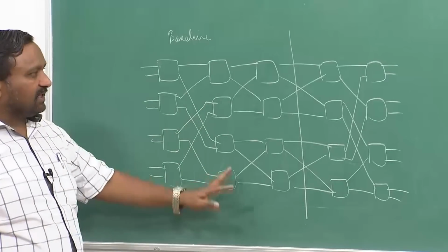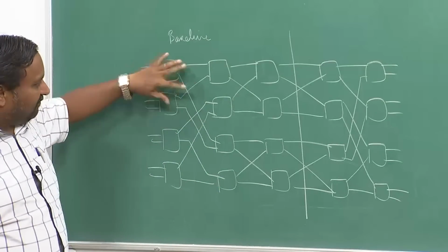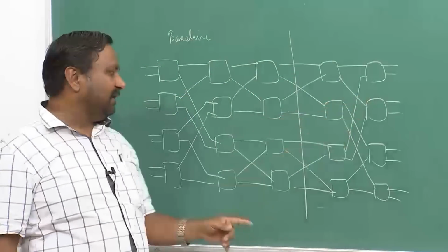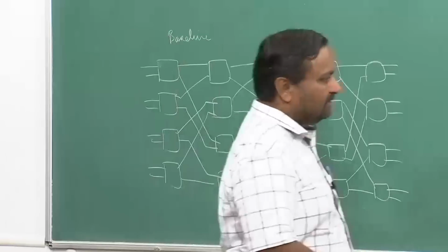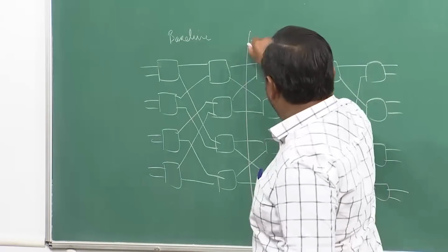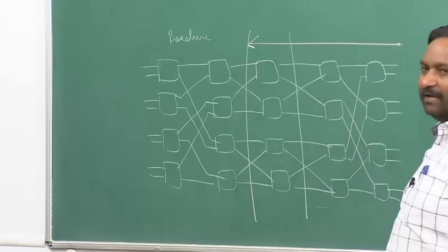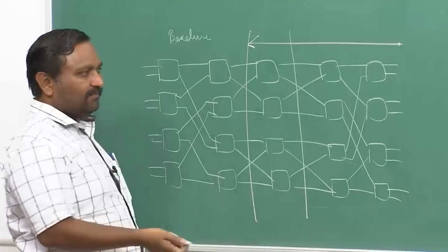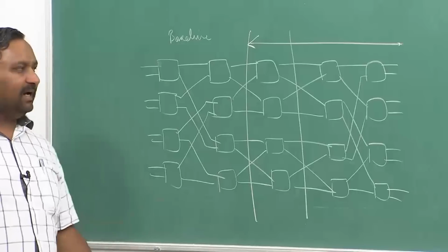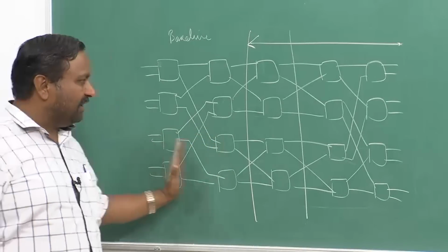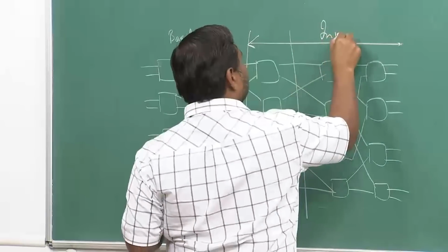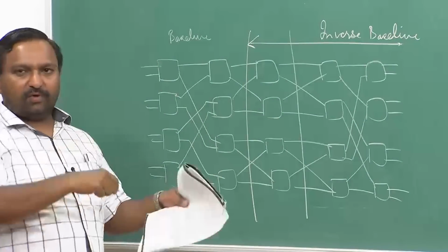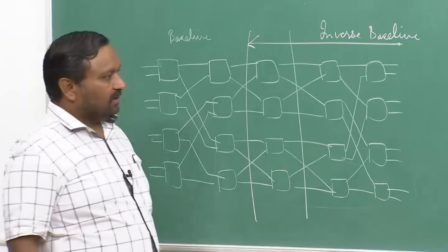And you can note, this is also a self routing system. You take this port, I am either going up or down, and then further from there it is self routing. That is what I tried in the beginning. If I take not this one but the other part, going onward all the way here, that is also a self routing network if you observe carefully. So both of them are self routing, but remember the interconnection pattern is not the same, they are different in every stage. This one, the baseline, can be built through a demultiplexer tree. The inverse baseline can be converted to this form by swapping the nodes here and there, moving them around.